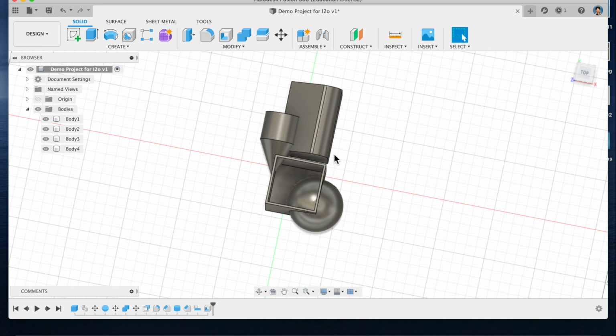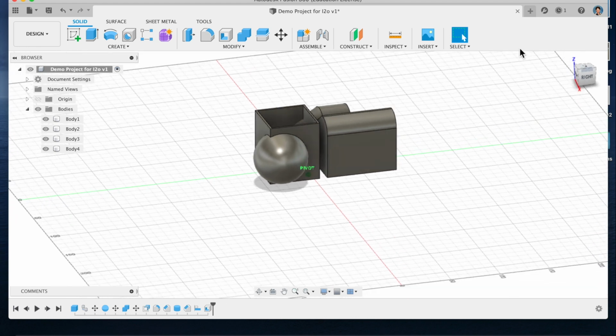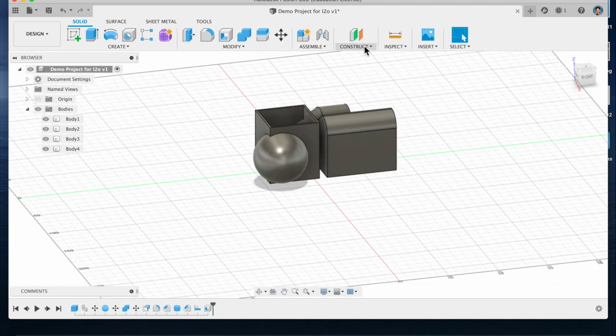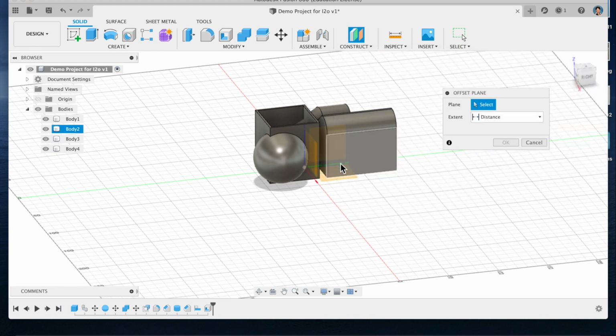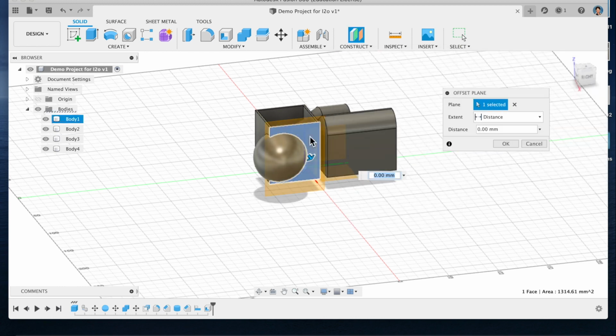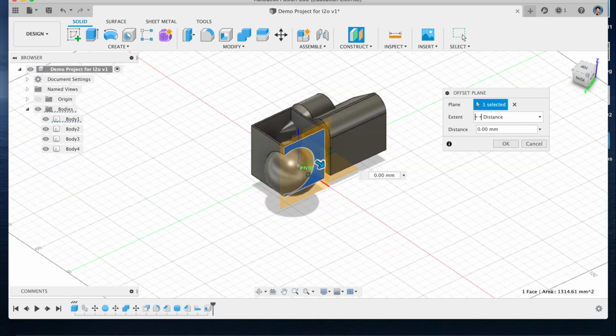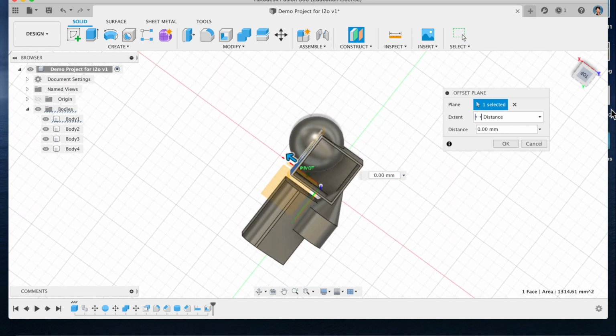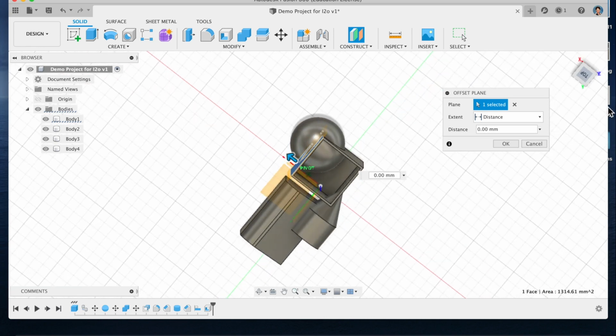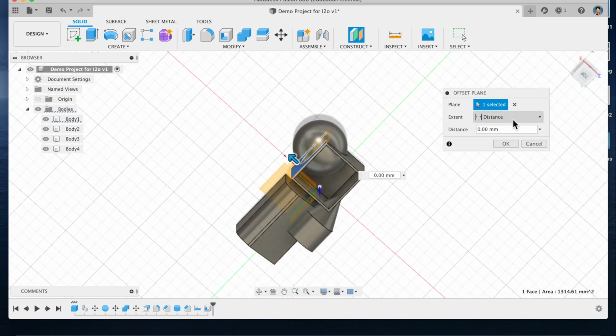How would you do that? There's so many things you can do with this. If you're getting a little more creative, you're going to end up using construction planes. You create the plane on another plane. A plane is like a surface area, right? So I just stuck it on the outside of that box. But maybe I want to offset it. I'll just drag it out here. How far? 100, no. How about just 12?